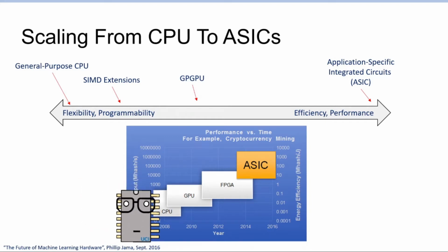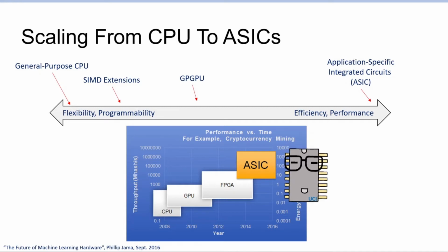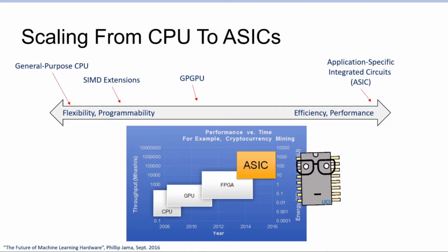So as we move from CPUs to GPUs to ASICs, the performance and power efficiency you can get is multiple orders of magnitude higher. This scale is even worse than the chart that we saw in the previous slide with the video processing application, potentially because the computation density of crypto hash mining is even denser, with simpler algorithms, less memory accesses, and more in-depth computation.